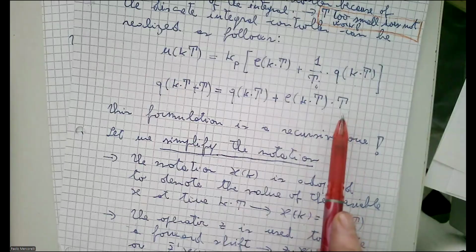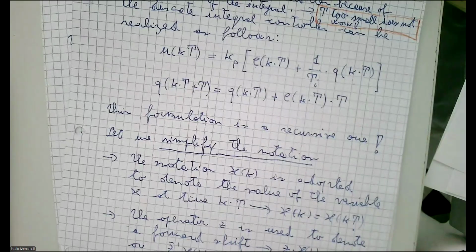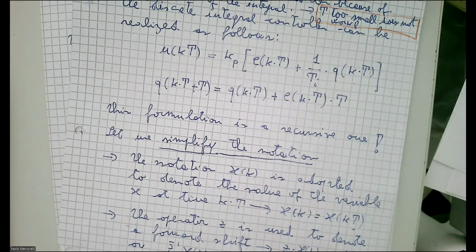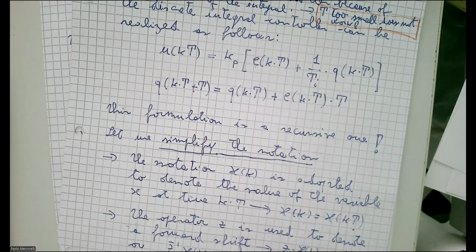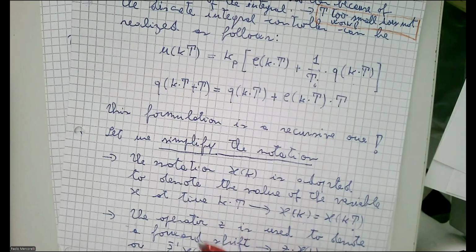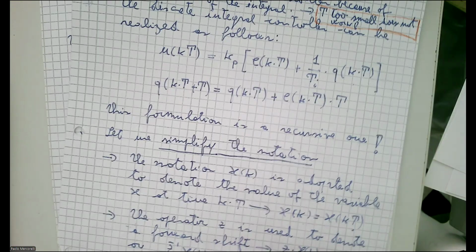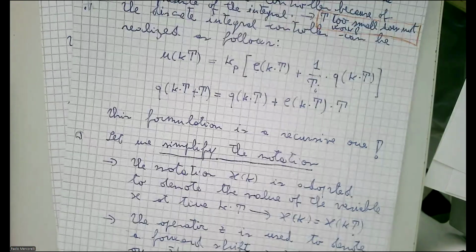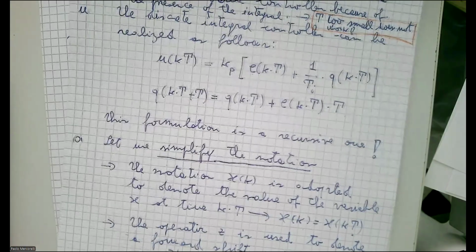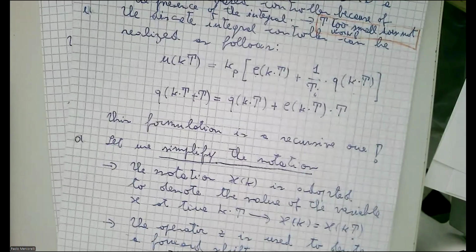This is the discretization of the controller, which for us guarantees the performance in continuous. But we want to implement it in the microcontroller. This means we have to analyze what happens in discrete form.